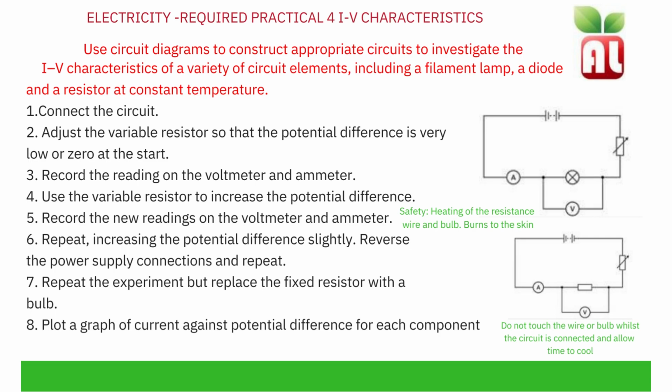Plot a graph of current against potential difference for each component. The safety aspect for this practical is that heating of the resistance wire and bulb could cause burns to the skin. Do not touch the wire or bulb while the circuit is connected and allow time to cool between readings.